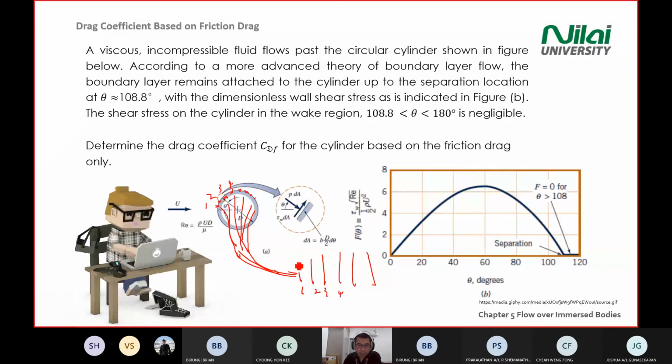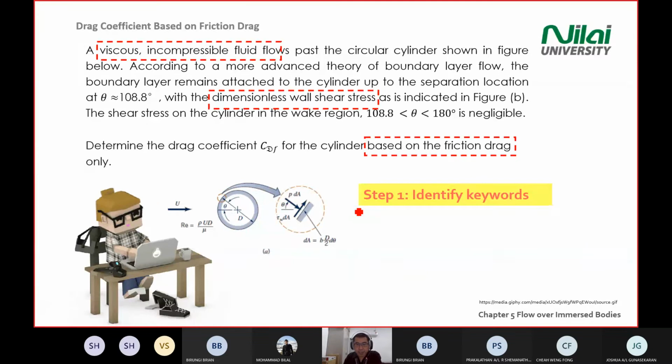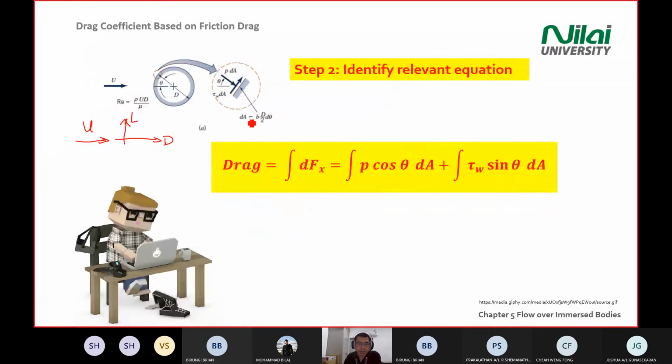This is a pressure gauge with mercury inside, so you can see the pressure P1, P2, and then you convert into force later on, then plot this kind of graph. You can refer to a standard given by this equation, then convert what you get from the experiment and find the coefficient.